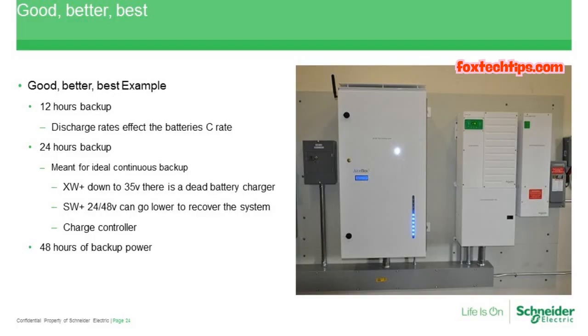One of the common questions that we get is whether or not you can do AC and DC coupling together, meaning that we're to have two charging sources. One is the grid tie inverters producing power from an array, and then let's say a wind turbine, solar, something on the DC side. We don't recommend that at this time. A lot of it has to do with managing who's charging and when, and that can create some issues within the system that we can overdrive batteries and cause something we call thermal runaway, which is unfortunately this photo that we see here on the right.